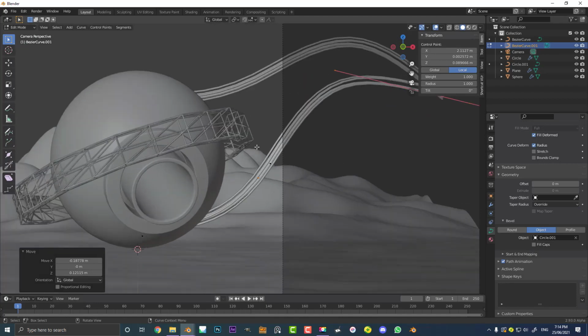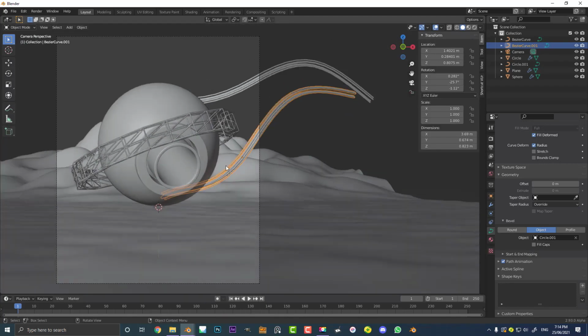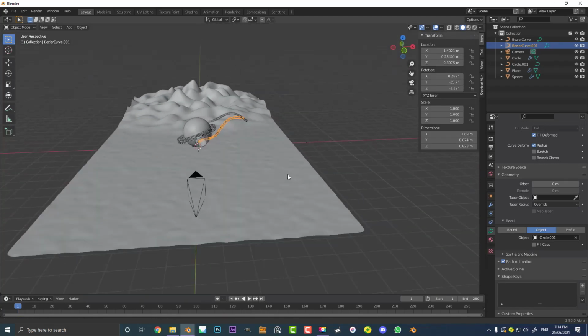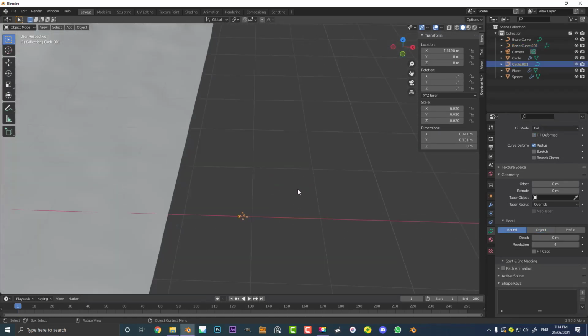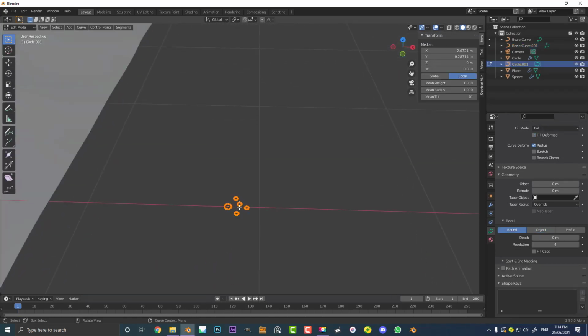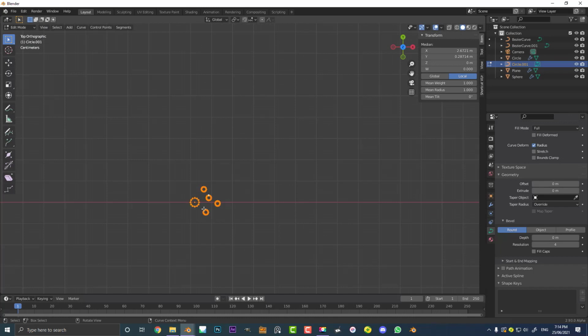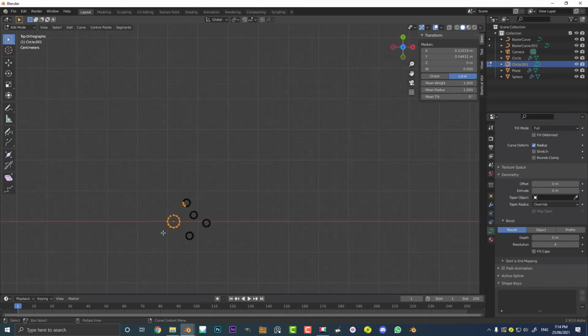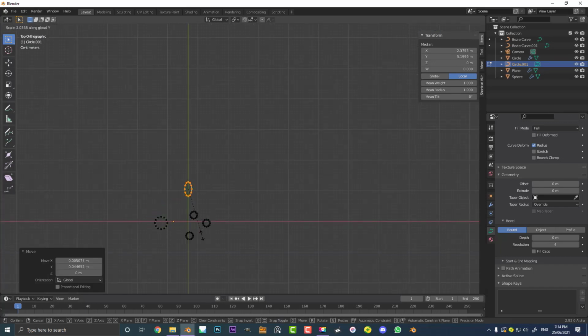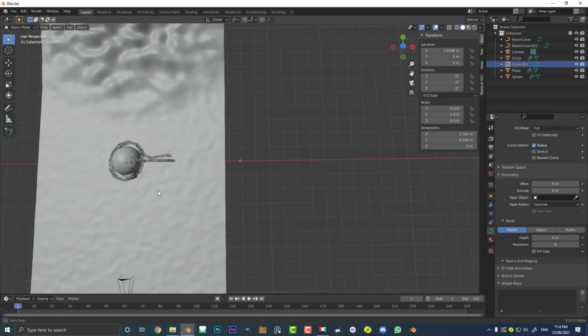So in your camera view, you can see this. At the moment, they're clustered together a little bit tight. So all we have to do is select our object that we're referencing, these little guys down here, go into edit mode, and grab them and space them apart a little bit more. Maybe scale one along the Y a little bit, make it look a little bit different.